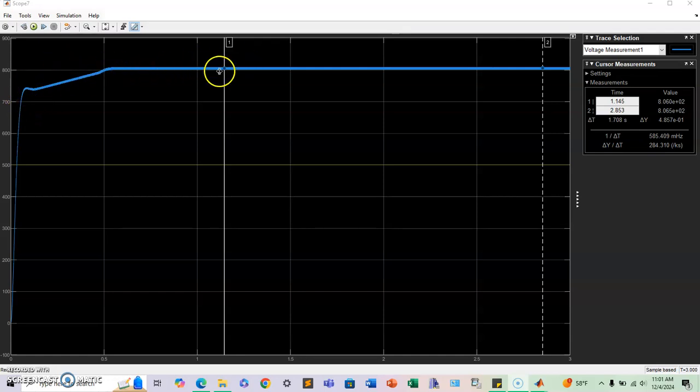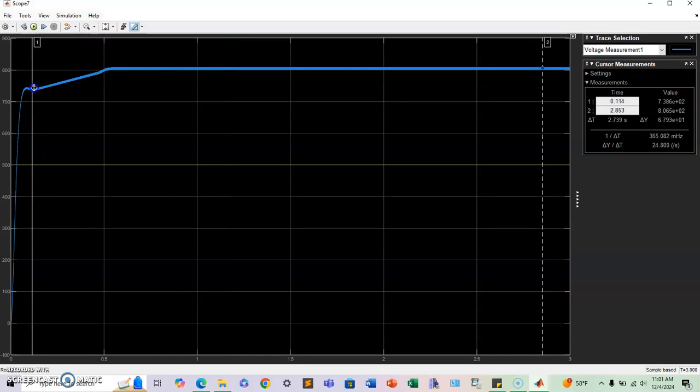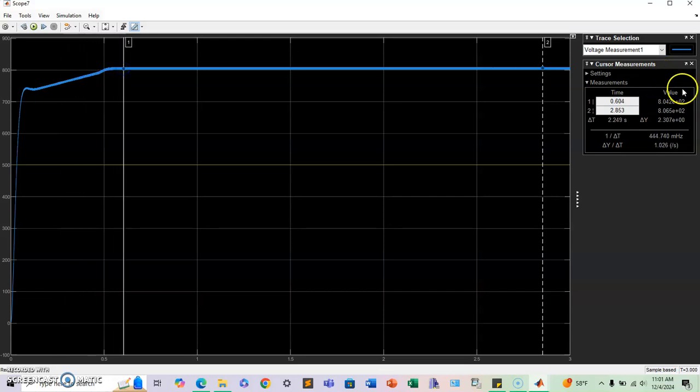See how it's like a PID step response, and it starts, and then this is how the ramp is starting to add into the pulse modulation, until it gets to more or less 800 volts. And see how it has very, very small ripple because the design is not with a PID. I can talk more about ripple later.